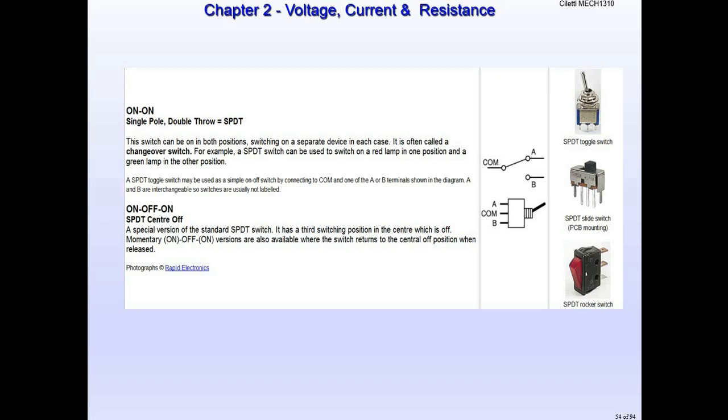All right, another one. So you're asking, well, what if we have two circuits attached? That's where we have our SPDT, our single pole double throw. Notice what's the difference there, okay? We have the one pole here that's a little bit different in the book. So there's the one arm, and it connects two different circuits, circuit A and circuit B. So that's why it's an SPDT, single pole double throw. So remember, the pole's the switch piece, and the throw's how many different circuits it's connected to.